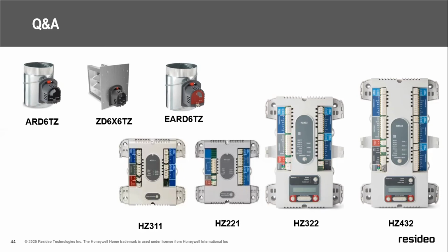And so you would have the ability by closing a dry set of contacts on the equipment interface module to kick on the dehumidifier at the same time that you're turning on the blower and sending that warm, dry air to the zone that needs dehumidification.